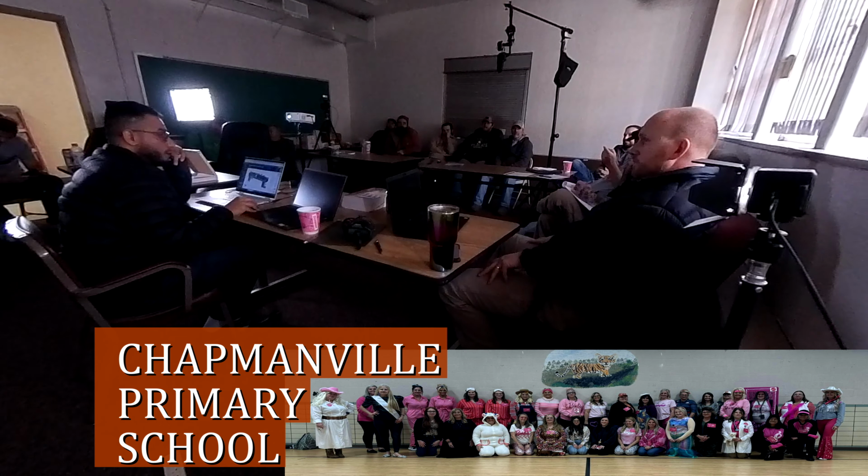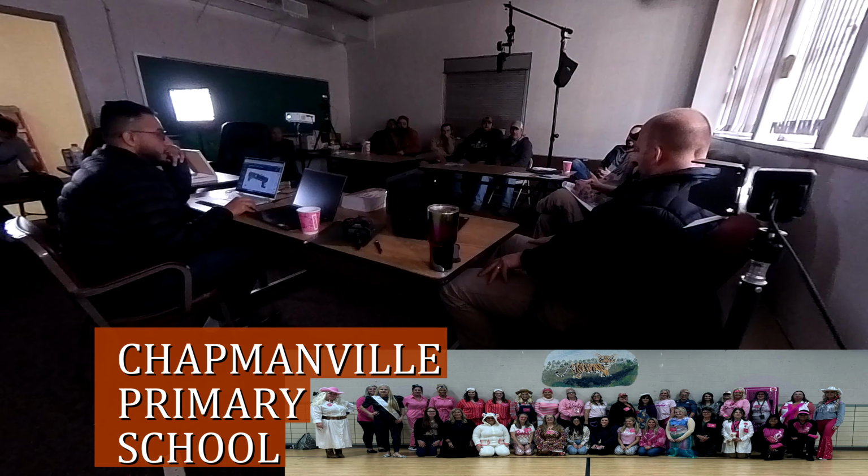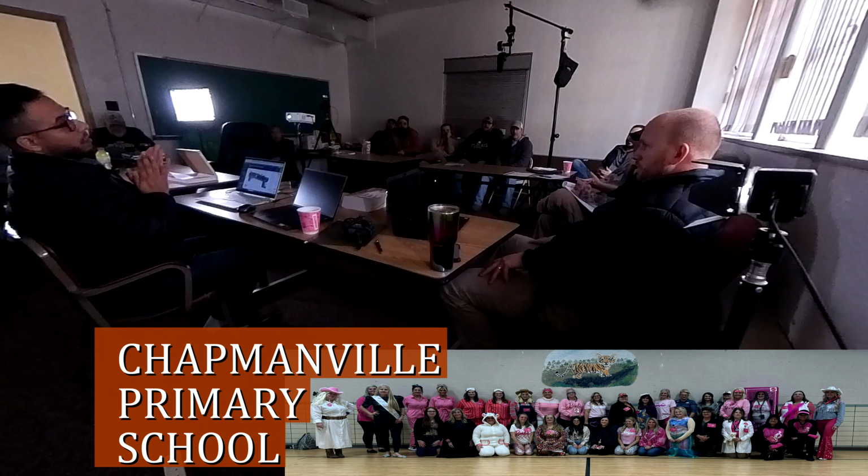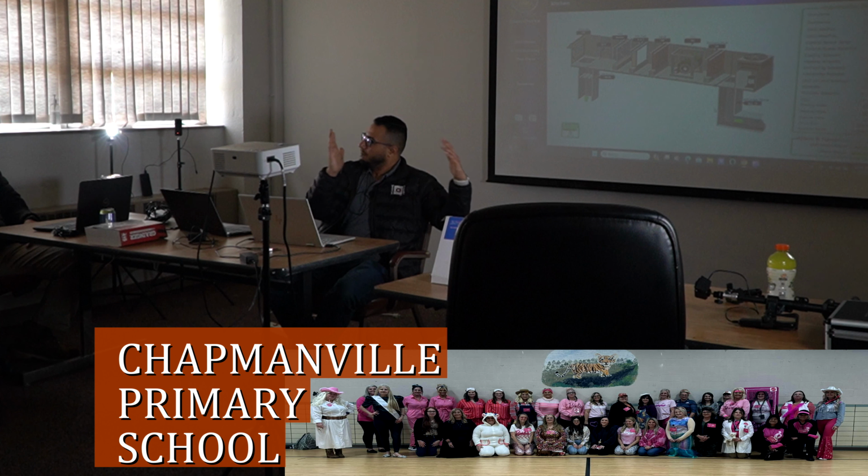Yep. So the only two times I would be closing that outside air would be if it's really, really cold, or it's really, really hot, or it's really, really rainy. So that means if it's really rainy, you probably want to use the summer mode, because that will keep your equipment running and shut down your outside damper completely.